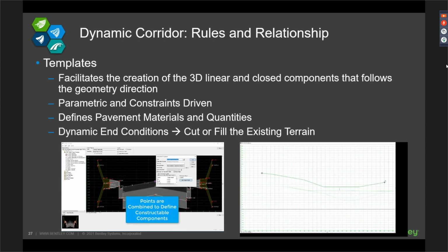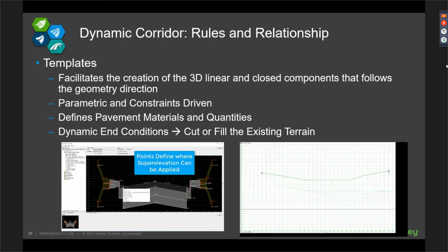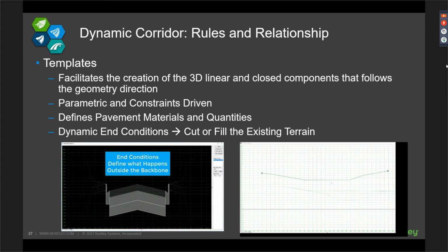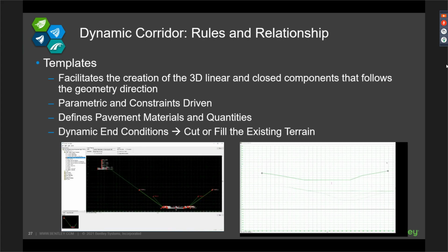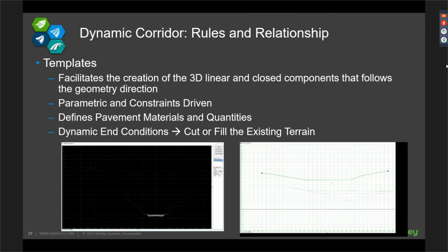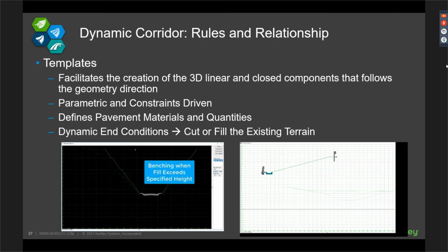Also, DWG can be readily opened inside any MicroStation-based software, which includes OpenRoads. But of course, it will stay as CAD, so probably you can just use that as a reference. The civil information there is not going to be intact. So you have to use LandXML to facilitate the exchange of civil data between the two software.